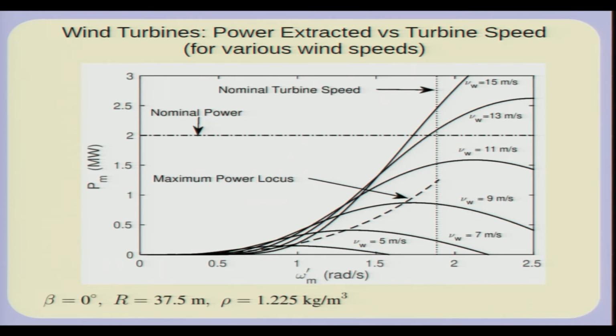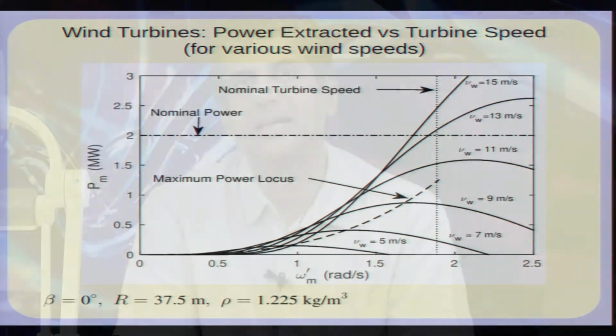Now, a synchronous machine, we know that if it is connected to a 50 hertz supply, it will also rotate at 50 hertz. So, the output terminal voltage frequency is directly related to the rotational frequency. On the other hand, if you use some other kind of machine, say an induction machine, which is slightly different. Well, I should use the word generator, not motor here.